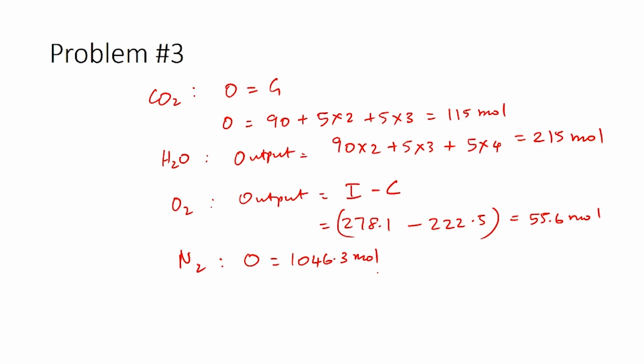We know that the stack gas is coming in at 1000 degrees Celsius. So, our next step is to perform the energy balance calculations for the waste heat boiler. Since all these gases are combustion gases, we can use tables from the textbooks or reference books where we can get information about the enthalpies for these gases.